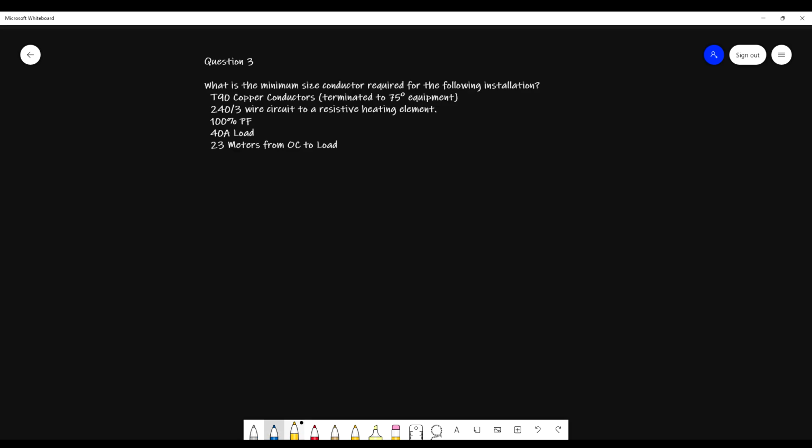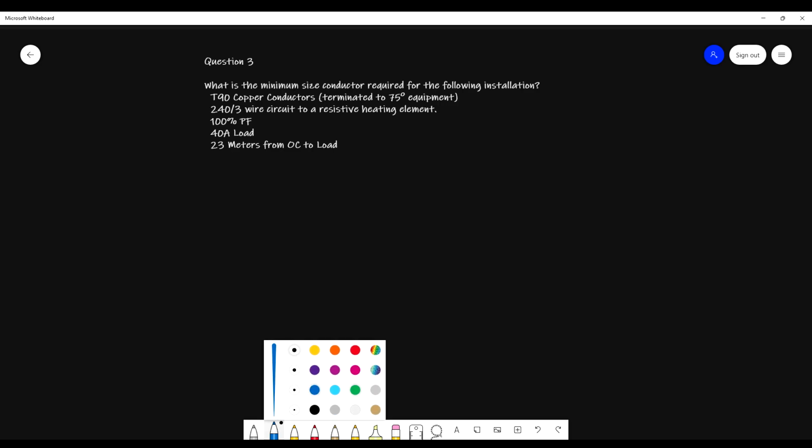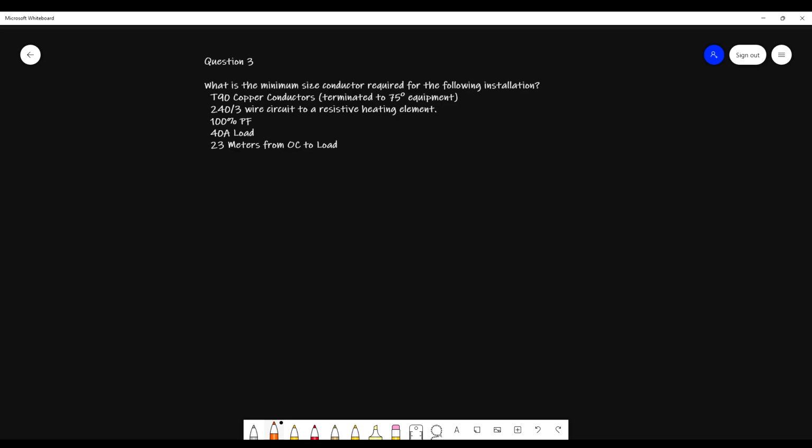Let's use orange today, and see how that shows up. Not that it really matters what I use. So we're going to calculate the K value, and it has to be less than or equal to the voltage drop times 1,000 divided by the current times the length of the circuit times the voltage drop factor. So again, we have this VD. We have to find the voltage drop, the amount of voltage that would be dropped in this circuit.